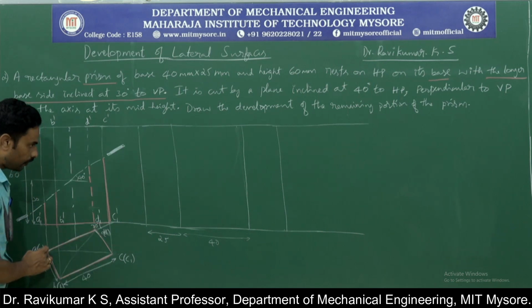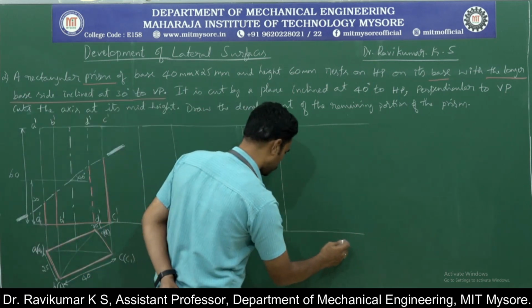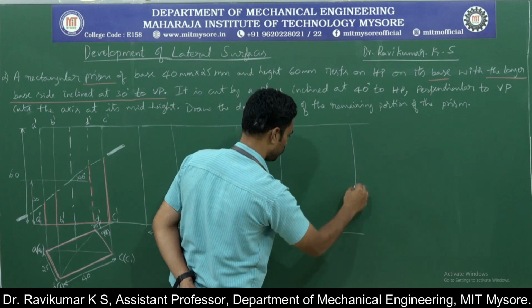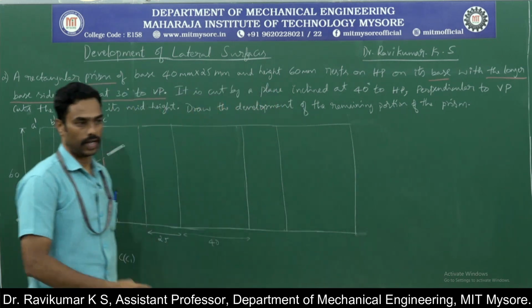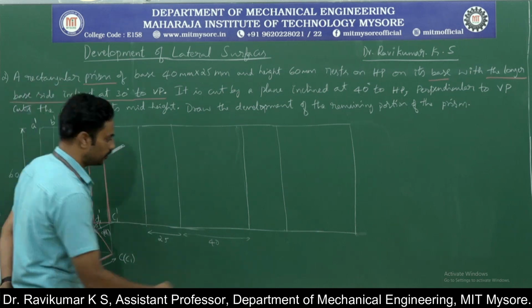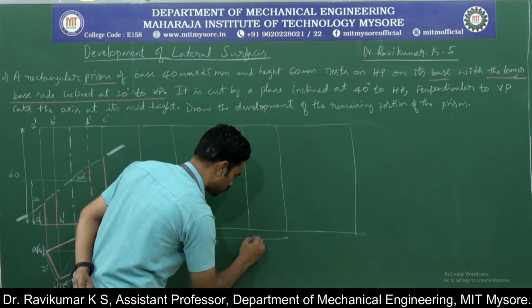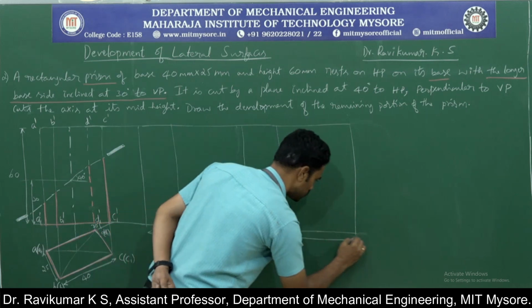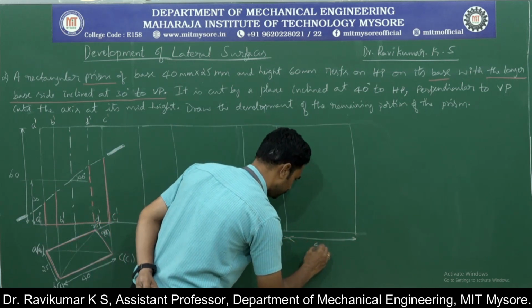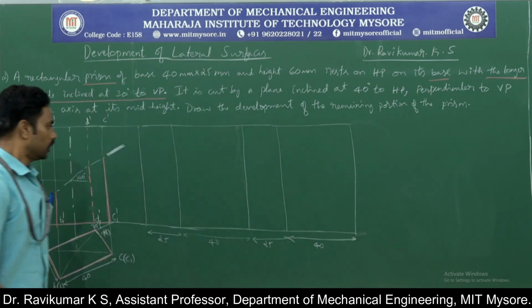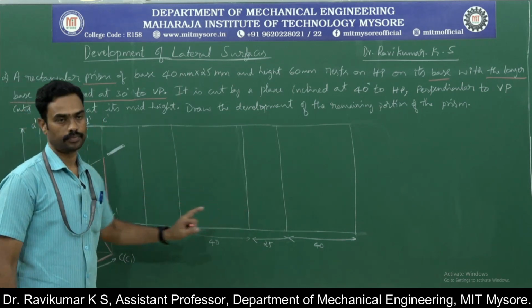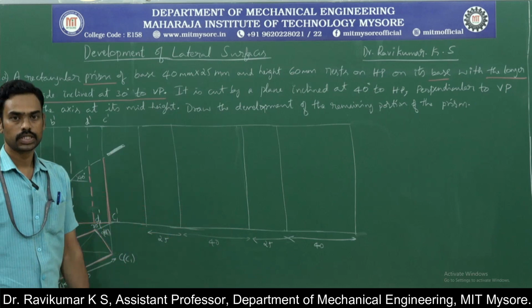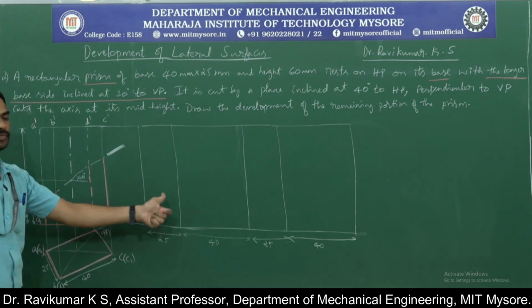Then from here to here 40, again 40, so from this 40 you draw a line and you chop off or erase the remaining portions. So this is 25 again and this is 40. Okay, this is where the development of the said solid should come, just beside the front view of the solid.